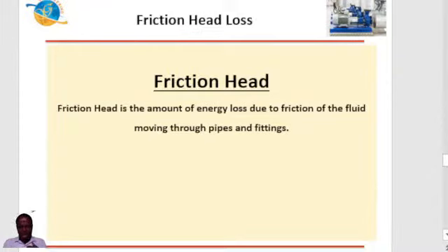I started by mentioning what pump head is, by saying that the pump head is that height to which the pump can raise the water to. And then I moved to what total head is all about, which is the difference between the height of the liquid in your discharge pipe and your suction tank level.